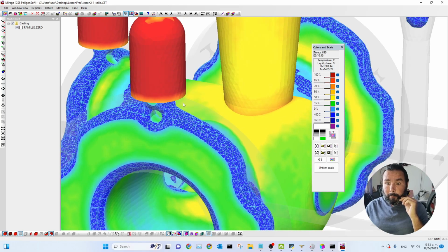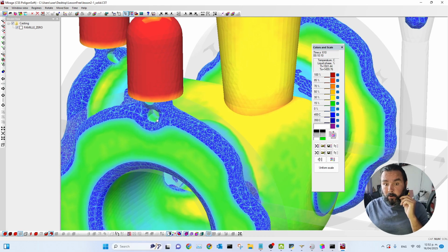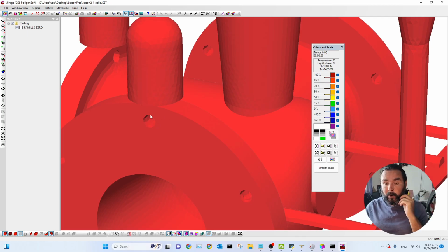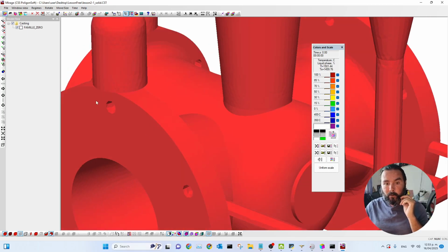There are two ways. First, in the 3D model, when we were designing our CAD, we could have filled this hole here and not left it. The second option could have been to simply draw a very small area here that doesn't contain many polygons of a volume containing sand, and use the virtual mold only starting from this surface, meaning fill the hole with sand in reality. Use real sand here to obtain the heat transfers between the parts, and what is outside, where the heat is truly emitted to infinity outwards, leave that with the virtual mold.